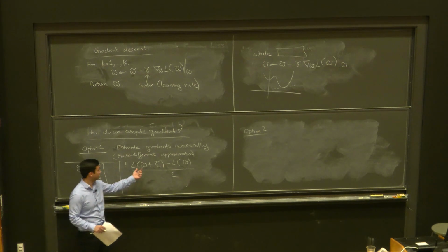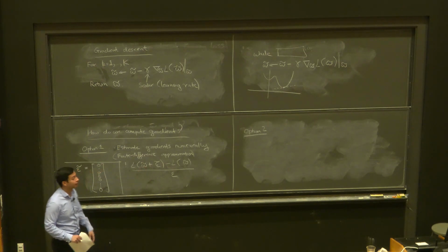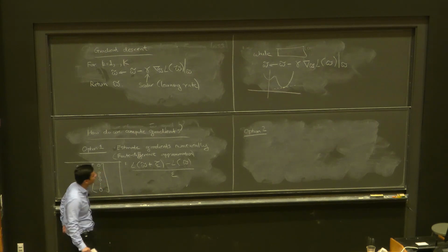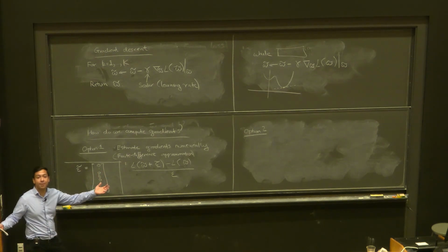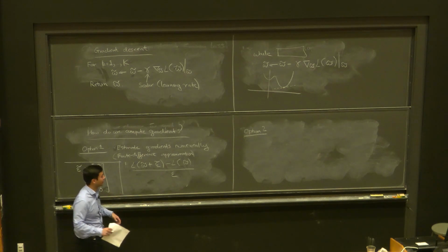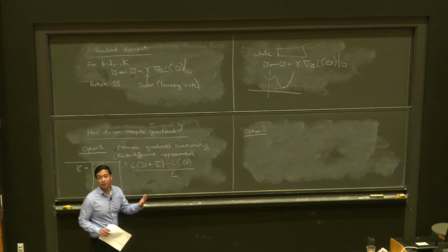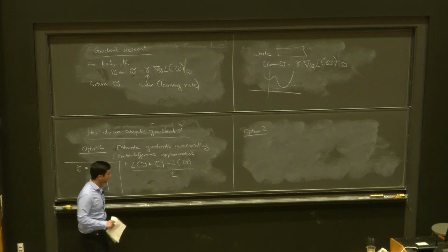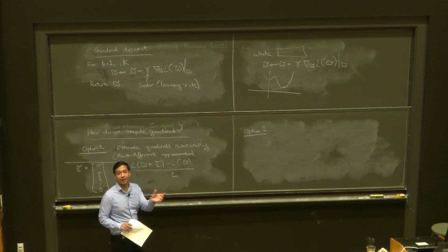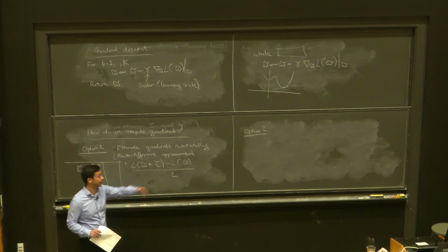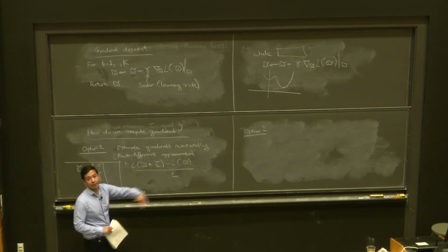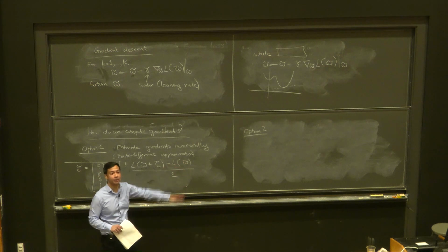That would be analogous to W tilde here. The robot does something, maybe moves around in some weird way, and then you can calculate some metric. There's a bunch of options. Cost of transport is one. That combines energy efficiency with speed, so you want to have the highest speed, but also keep the energy cost low. Or you could just look at raw speed, like how quickly the robot ran.